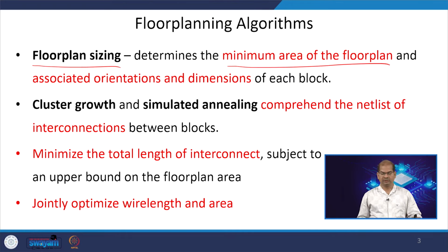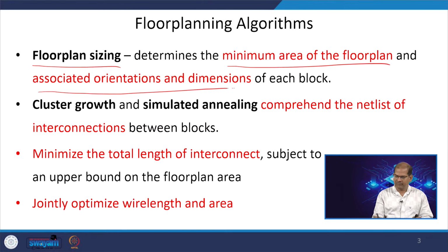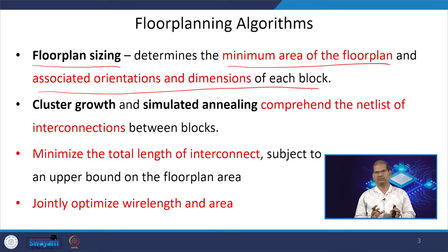The floor plan algorithm finds the minimum area of your floor plan and the associated orientation and dimension of each block. How the blocks and the block orientations should be placed in the silicon such that my total floor plan area should be as minimum as possible.